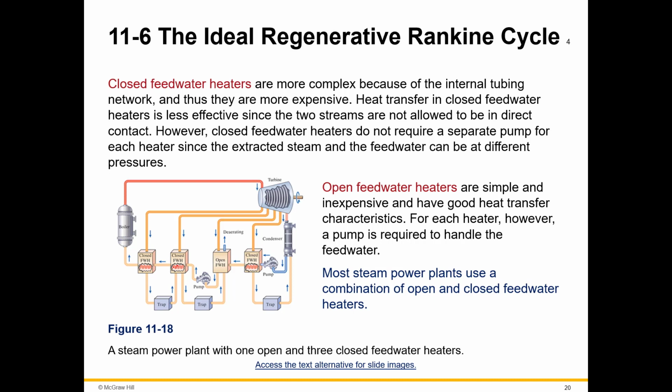Open feed water heaters are simple and inexpensive and have good heat transfer characteristics because they can directly mix. For each heater, however, a pump is required to handle the feed water, and that's to address the pressures. Most steam power plants use a combination of open and closed feed water heaters because the designs of each one are different, and even if they have power plants with multiple of these situations, not each one may be identical.